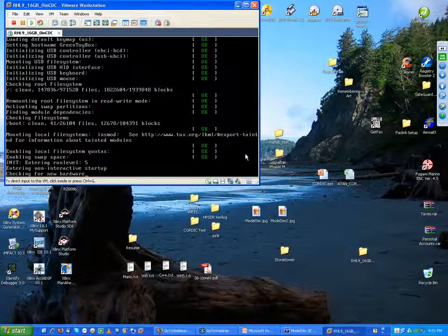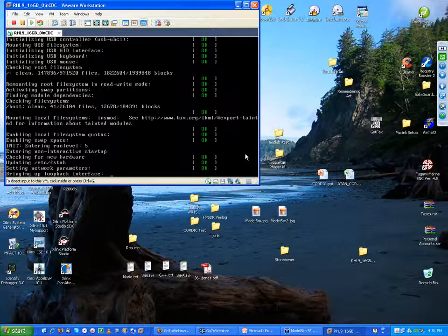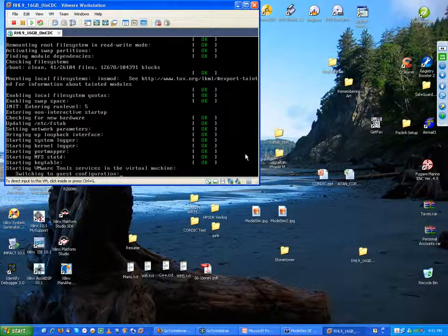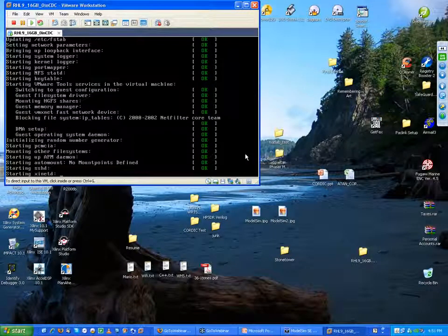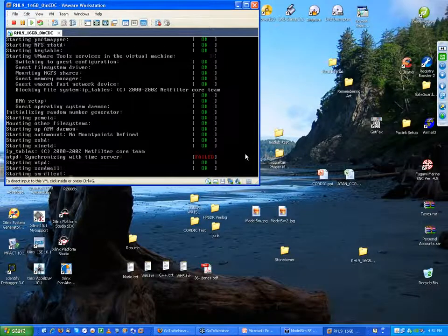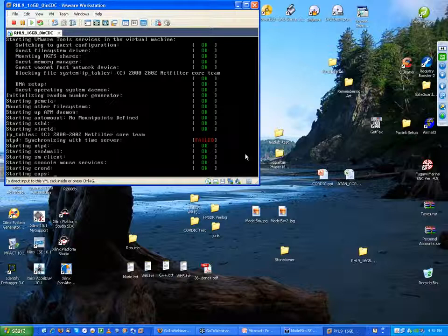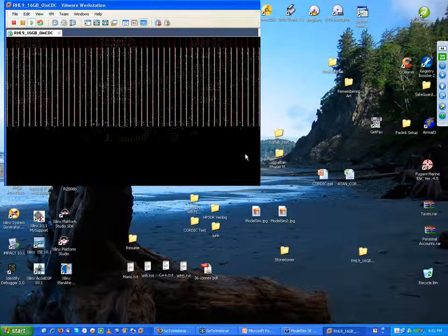I'm not sure. I think if there's something discrete, its position would be dependent on the phase increment, so it would move around if you move the phase increment. I'm not sure if it would be close to the baseline or close to your F sub O, or someplace else. It would just be at a constant location dependent on the phase increment. Now, I think you mentioned there was a DC offset. Explain what that was. I think they were essentially doing a truncation instead of a signed, biased round. Like if you round away from 0, right.